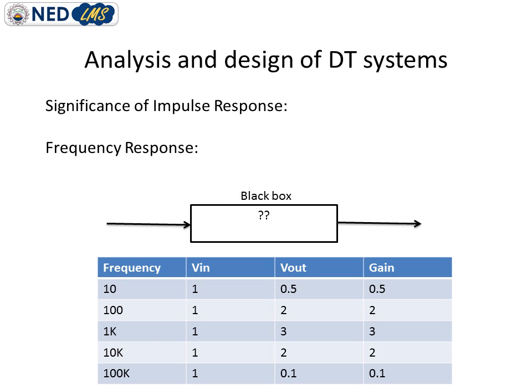You may notice that I am increasing the frequency gradually, keeping my input voltage the same. By doing this, I am getting different values of output voltage, and by using the information of input and output voltage, I am calculating the gain. This type of information is useful to plot the frequency response of this particular system.